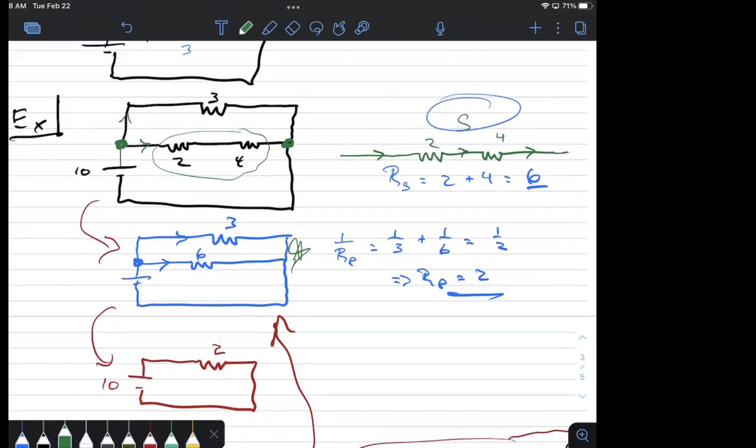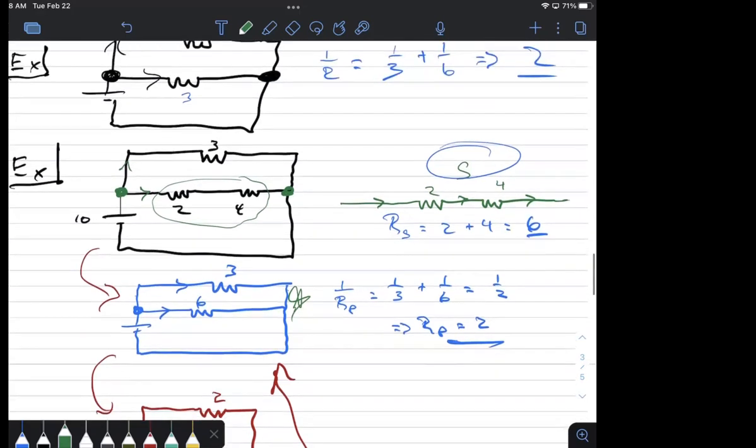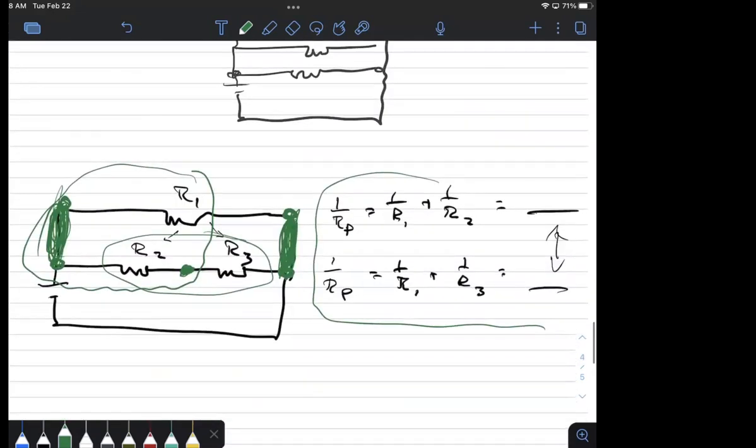So, there's good news and bad news. The good news is there's only two choices. They're either going to be in series or parallel, or there is a third choice. The third choice is they're in neither yet, but after you simplify it some, now it'll unlock that they're in series or parallel. What I mean is, with this example, R1 is neither in series nor parallel with any of them yet. But once I've simplified 2 and 3 together, now R1 is in parallel and I could start working on him. So that's the good news.